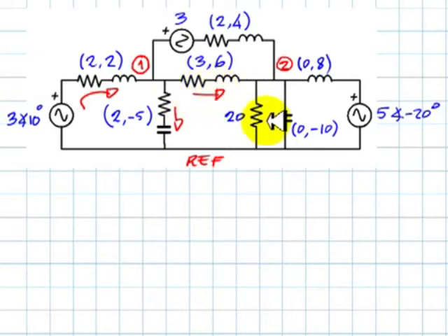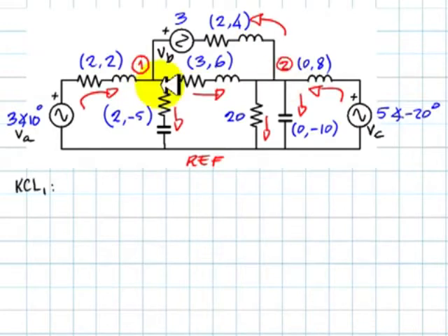And after that, we immediately realize there is no controlling source, so no controlling equation, there is no current branch, and all we're left with is only two KCL equations. Let's write those two KCL equations, one for node 1 and one for node 2. Currents entering the node, there are two, this one and that one. Currents leaving the node, there are two as well, four terms.